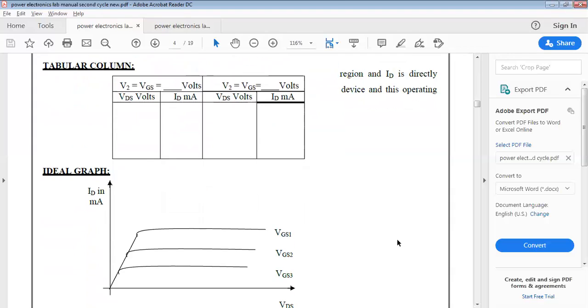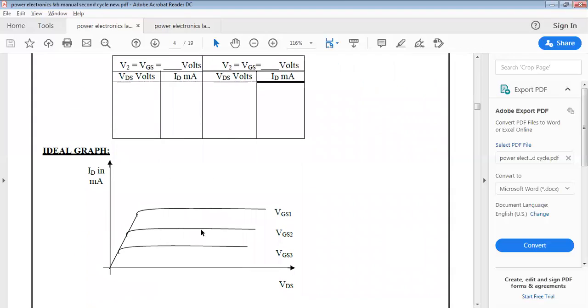That is what is indicated in this diagram. If you conduct the experiment for a very low value, just above the threshold voltage of 3.5, you can see that the current starts increasing linearly, and as you increase the supply voltage, ideally we are expecting the voltage across the drain to source to be zero, but since it is a non-ideal device, we are expecting some small voltage across the drain to source with an increasing current.